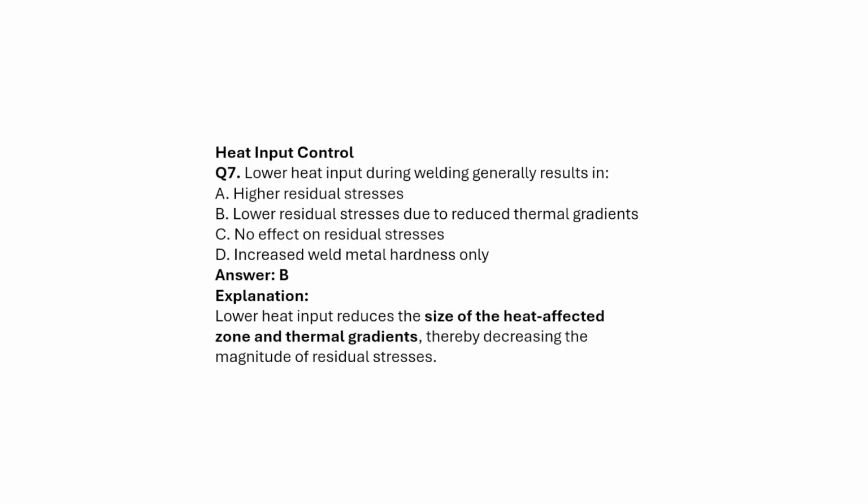Lower heat input during welding generally results in: higher residual stresses; lower residual stresses due to reduced thermal gradient; no effect on the residual stresses; or increasing the weld metal hardness only. So answer will be B. As we see, if the thermal gradient increases, the residual stresses increase; if the thermal gradient decreases, the amount of residual stresses is reduced.